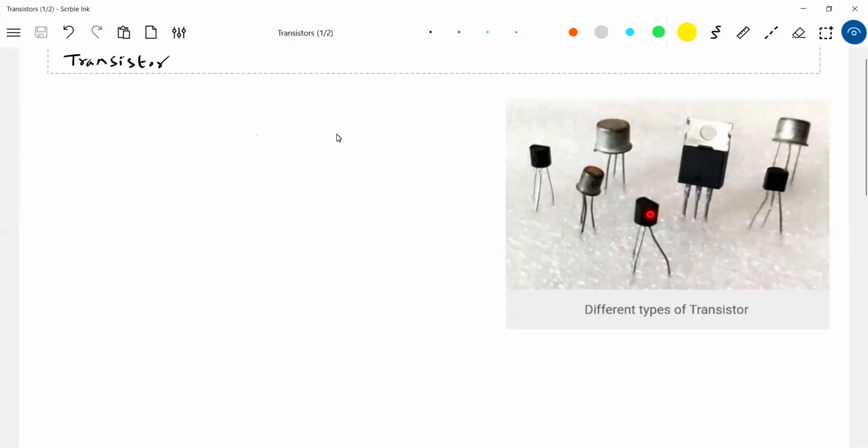This is called a power transistor. These are very small, tiny, like buttons in fabric, small buttons of that particular shape. These have some metal, where you can see metal, to dissipate heat. Where plastic is there, they are low power transistors; where you can see metal, they are high power transistors. This is completely a power transistor to dissipate heat generated in the semiconductor material. For that purpose, this shield is brought here. It will drag heat from the transistor and give it to the surroundings.